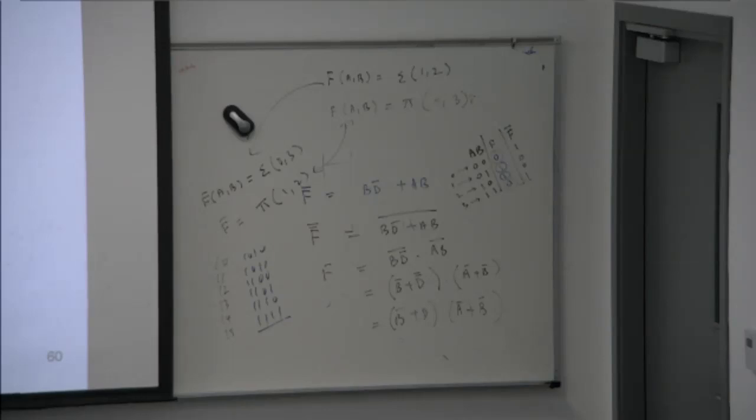Where is 2? What is the code for 2? 0, 0, 1, 0. Got it? How do you do it? I did the animation. This 2 belongs to this, this 8 belongs to this, this 10 belongs to here, and 15 belongs to here. Got it? Now this is the sum of the minterm form. We fill all of the entries. And then D, don't care. What are the don't cares?